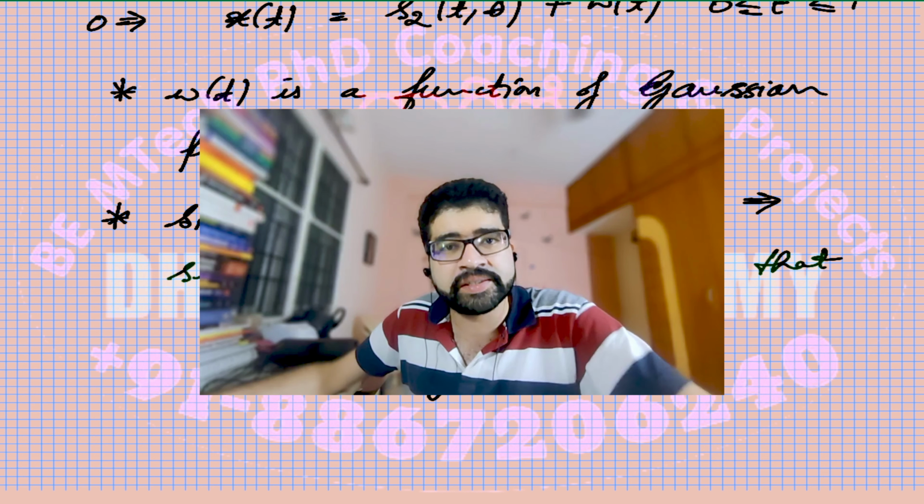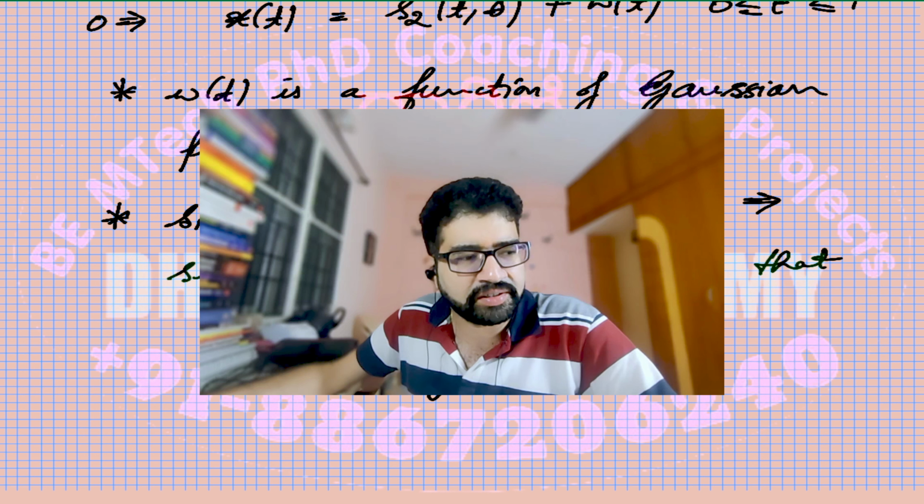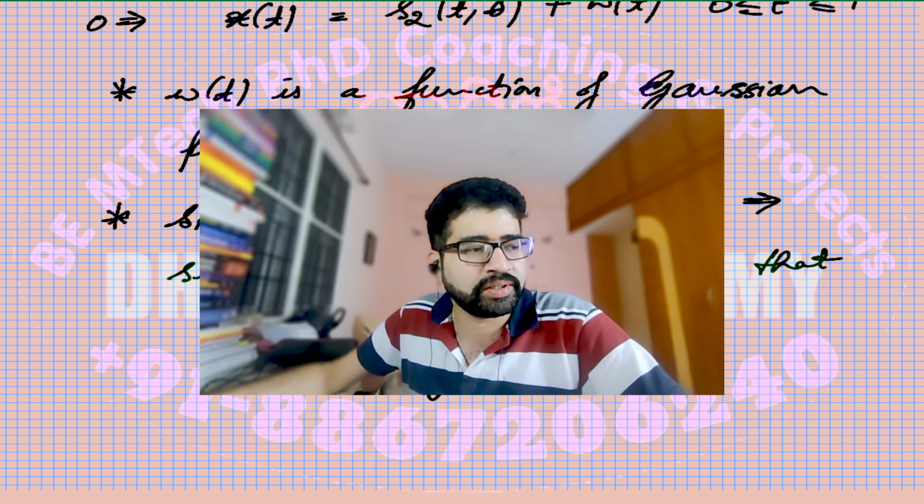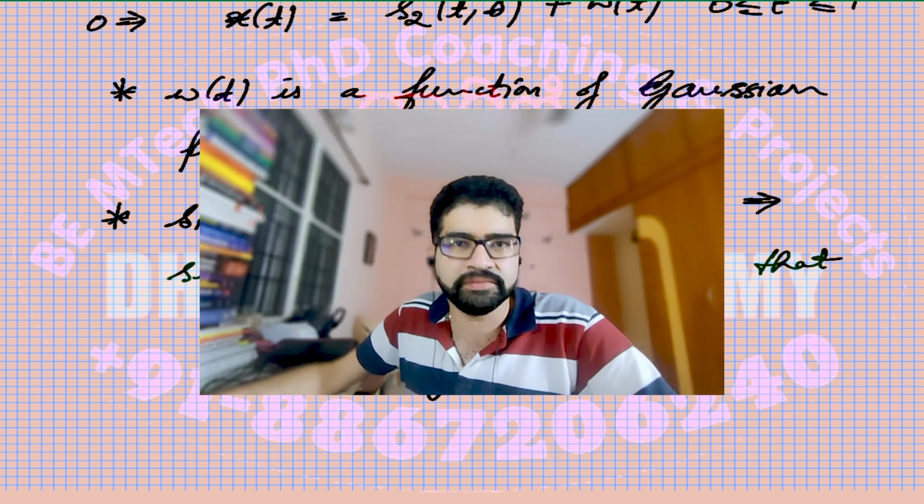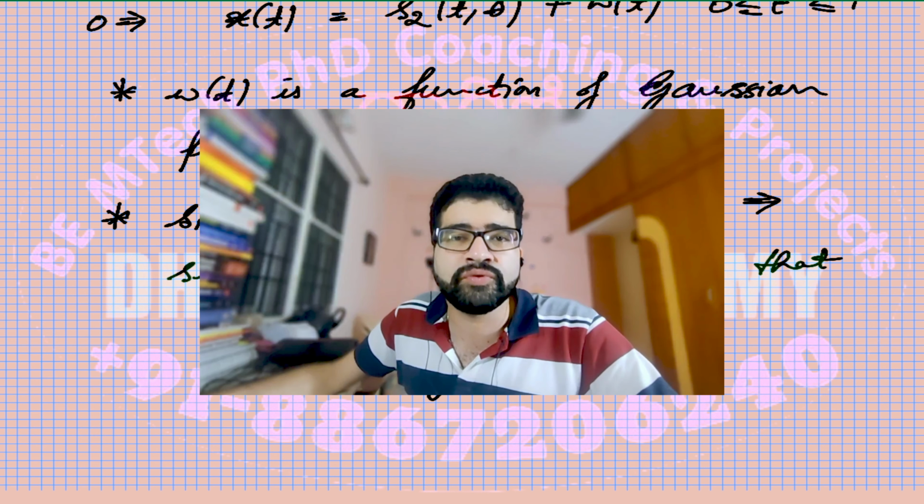But still I have to design a technique so that you come to know what the phase added by the channel is, try to remove the phase from the received signal so that the phase has been compensated, and you extract the frequency component fc from there so that you can process.